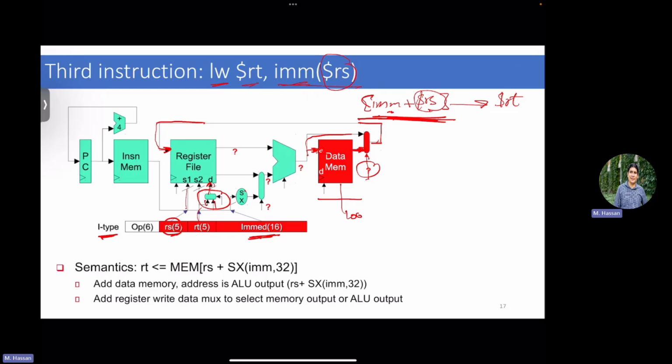We're going to have this discussion later on, but usually you build a ROM or a combinational logic that takes the opcode as an input, does some circuitry, ANDs and ORs and muxes, and then feeds the selection lines. The decode unit is one of the most complex in modern processors because there are so many instructions and you have to optimize it.